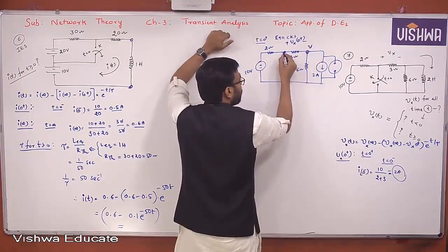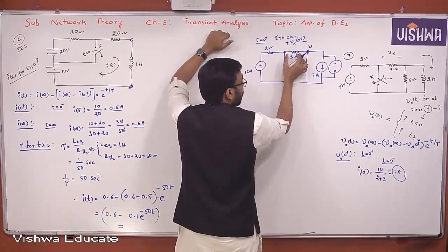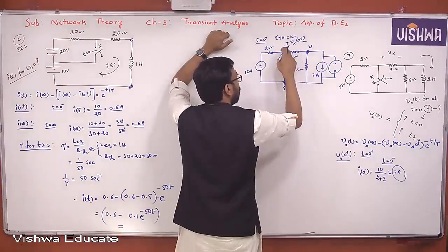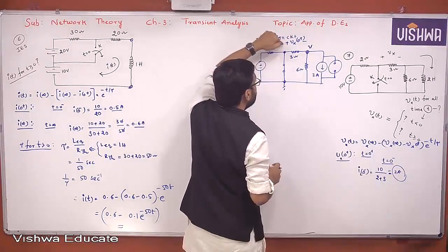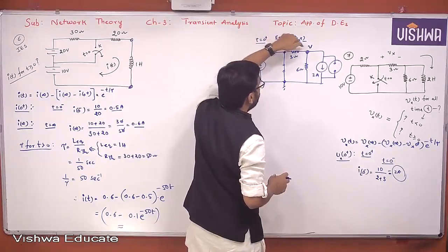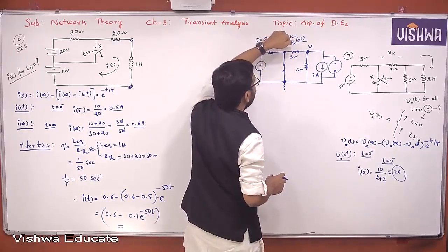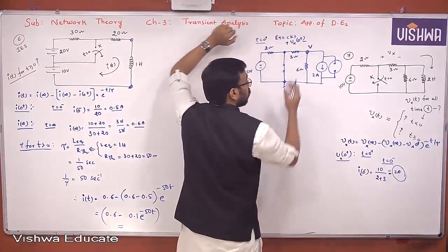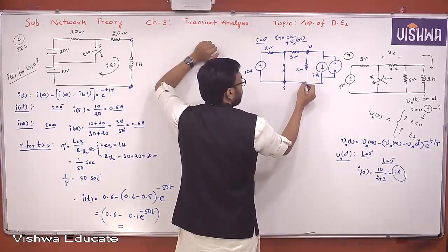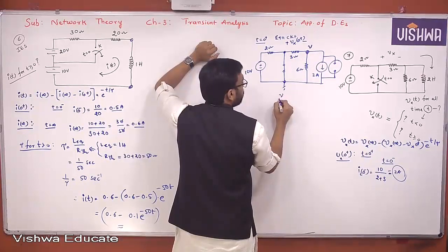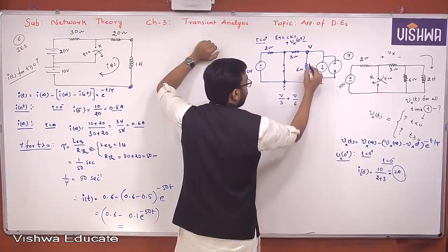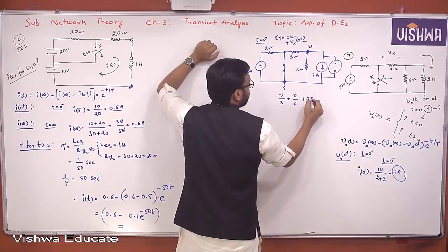Now this is also 0. The potential difference between these two can be easily calculated. Now Vx of 0 plus can be written as follows. Since this is higher potential and this is lower potential, but you want the voltage the other way, there is a mismatch in the polarities. You can say Vx of 0 plus is equal to minus V. So let's find the V here. V minus 0 by 3, V minus 0 by 6, and plus 2 leaving current. That's it.